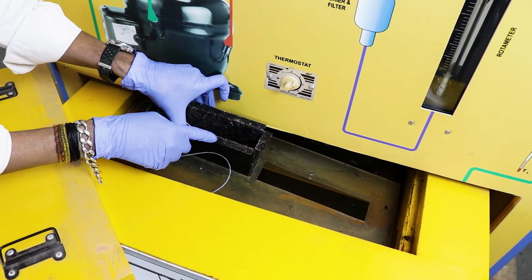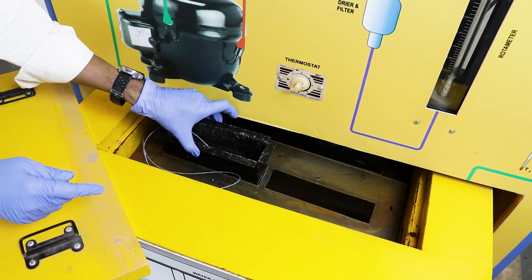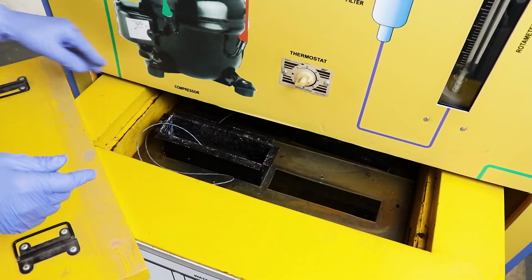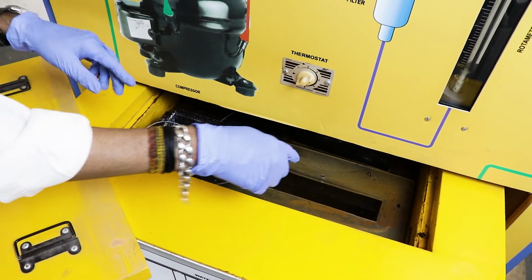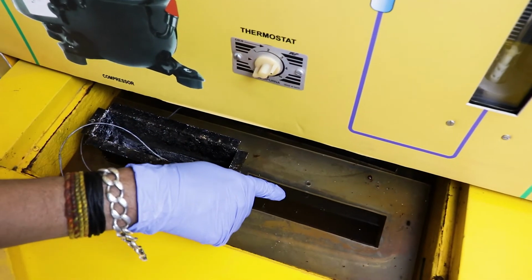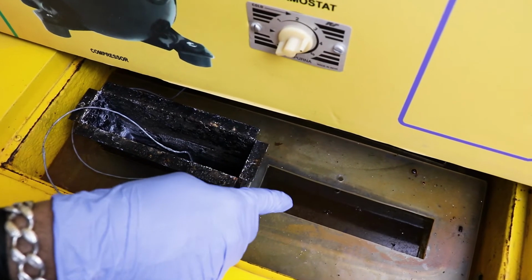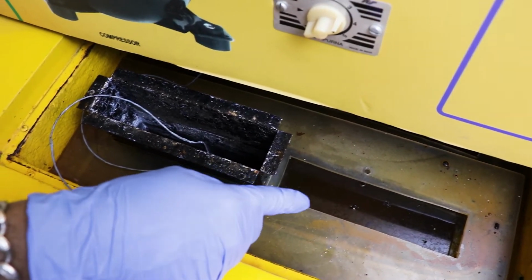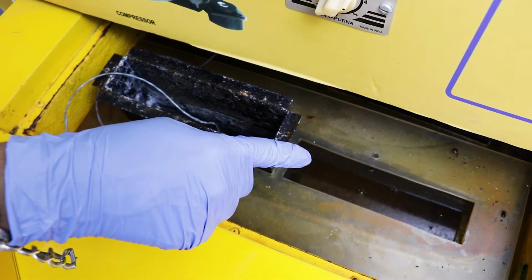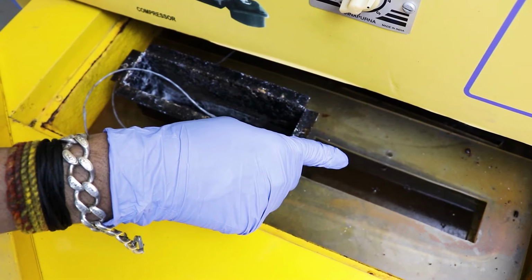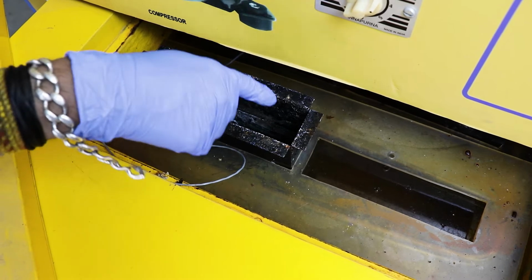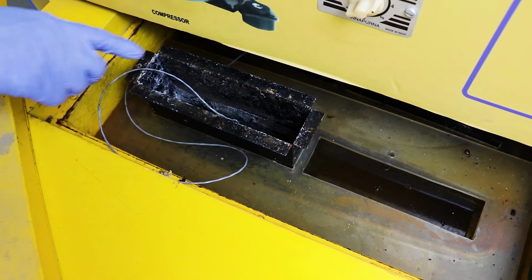We have many such containers inside this, and they are surrounded by the brine solution. You can see that it is a brine solution. That is a secondary refrigerant. There are tubes inside this. The tubes have the chilled refrigerant inside them, which cools the brine solution. And the brine solution removes the heat of the water inside these ice trays here, and that is how the ice is formed.